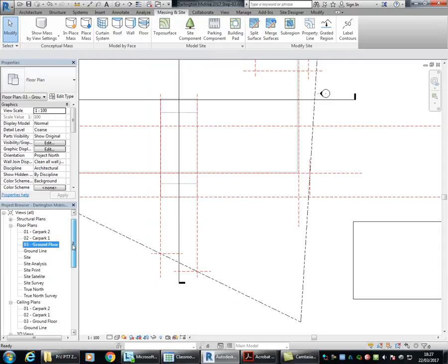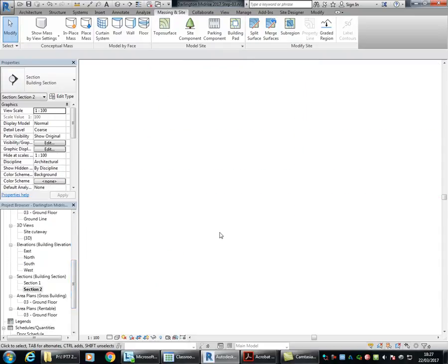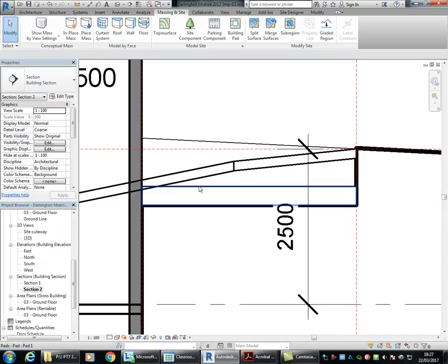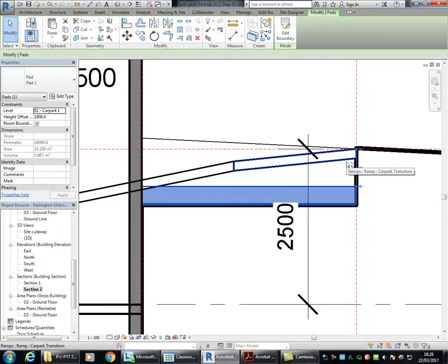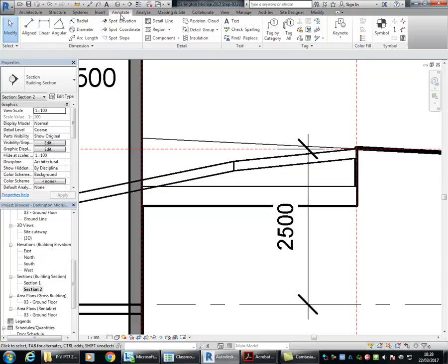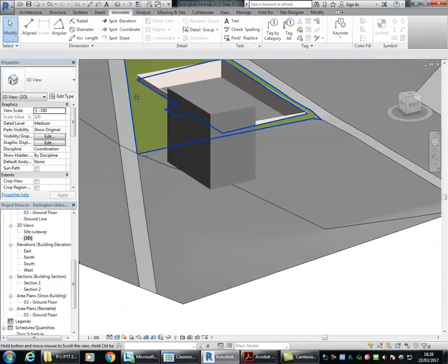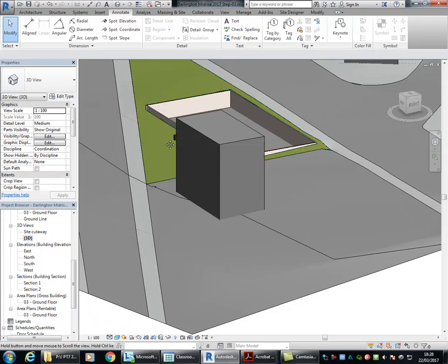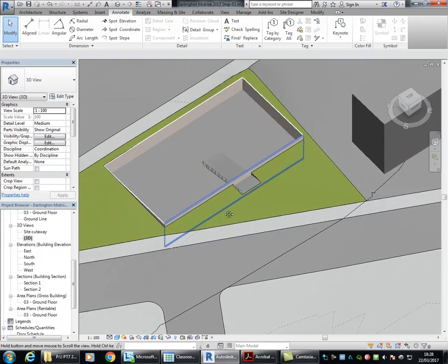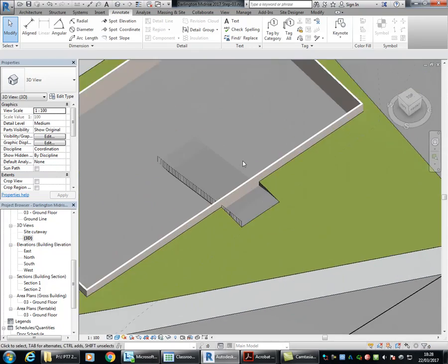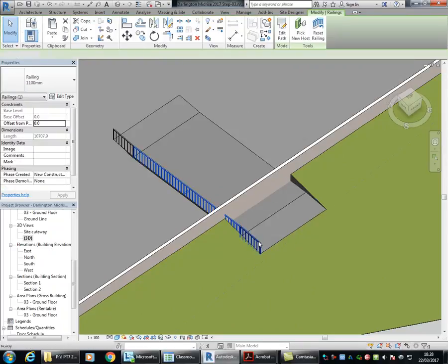you could, but now I don't usually bother with that, because I've just found with all the issues you have, getting the earth cut pattern to show properly, and getting the ground line in elevation, it's often easier to do those things just with 2D annotation, rather than try to fiddle around doing everything in 3D. So, and that's really one of the keys with Revit, not trying to over-complicate it and do all the things that it can do, especially in 3D. When you don't need to do them, it's often easier not to.